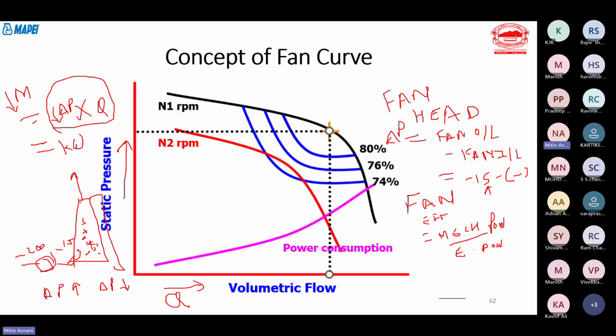Okay. So what will happen when you increase the height? Your natural draft also increases. If the natural draft increases, automatically the fan has to do less work, because the total work is always constant. The same work is transferred to the stack. Means, there are two people, one man has another man in front of him, so the work is shifted to the other person. So you have to learn the same concept about the natural draft.